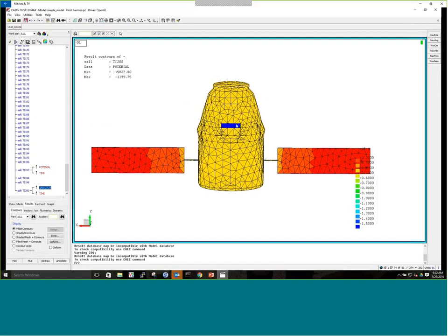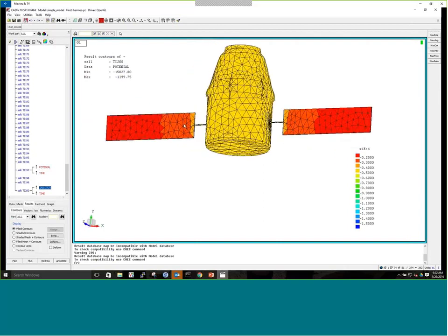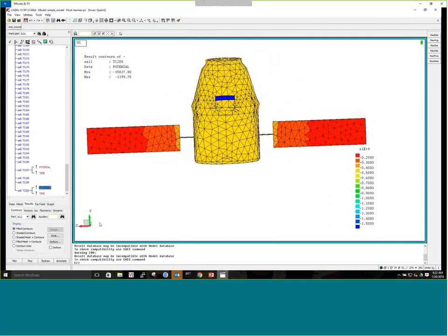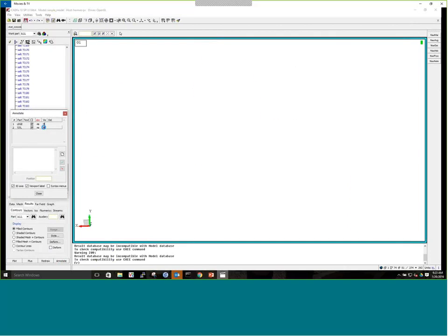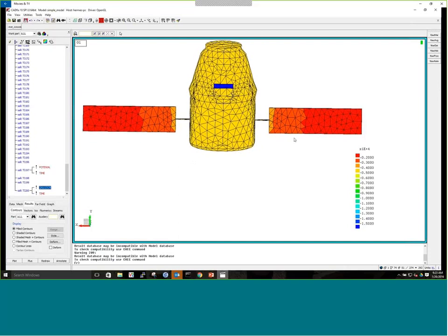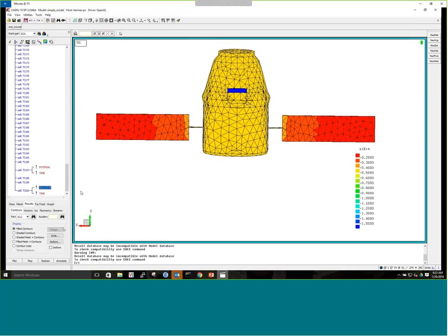And they are actually charged less negatively than the rest of the vehicle. And you can see sort of a gradient developing between the solar panels and the rest of the vehicle, going from a more neutral charging to more negative. So this vehicle charges negatively with respect to the plasma. Now we can get a little more insight by actually doing the animation. And so that's what we'll do here. We can modify our graphics options as we want. There's a lot of different options for the graphics and how you plot. You can have a fixed scale, logarithmic, all kinds of options.